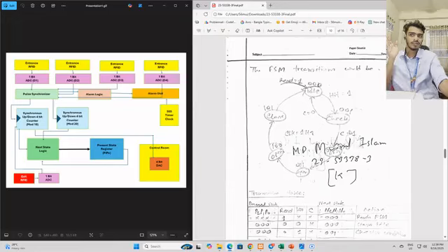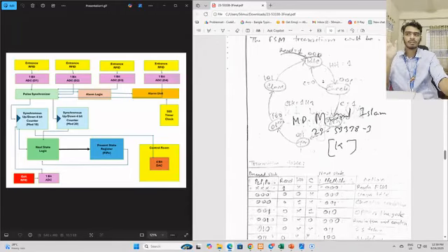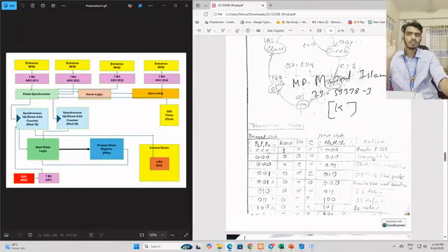But if I get a high, that means the check is valid, then the gate is turned on, the gate is open. It will stay open for 3 clocks. I have used a 1 Hz clock, that means 3 seconds, so it will stay open for 1 clock, 2 clock, 3 clock, and then it will close. After the 3rd clock it will close the gate. Once the gate is closed, on the next clock it will go back to the idle mode, and that's how the cycle continues. And there is a reset button, so if I press reset, then wherever I am, it will go to the idle state. So this is our transition table, so you can look into it.